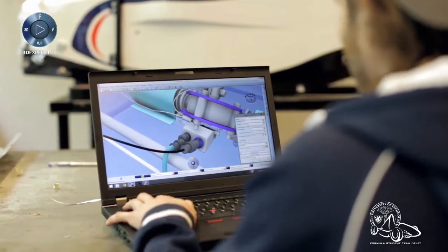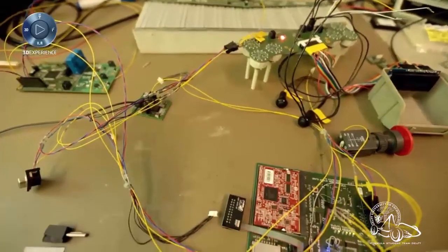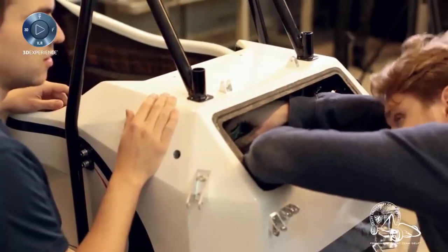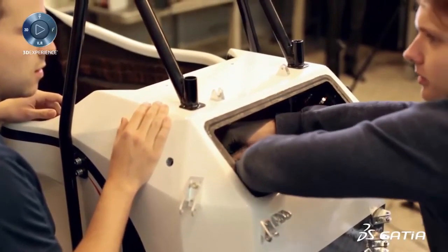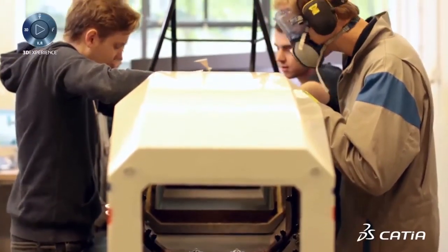We use flattening to design the drawings for the wiring harness, which we printed full scale, which was a big help during production. Then we calculated the length of the wires, and we used these during the production. We put them on the drawings. They were perfect in size, which meant we could really go quickly through the production.